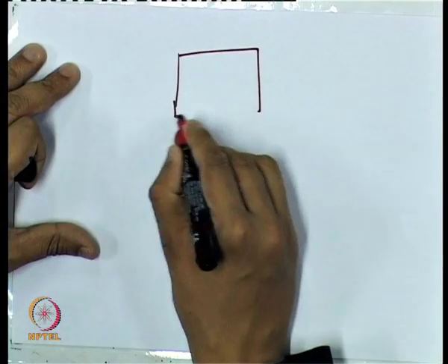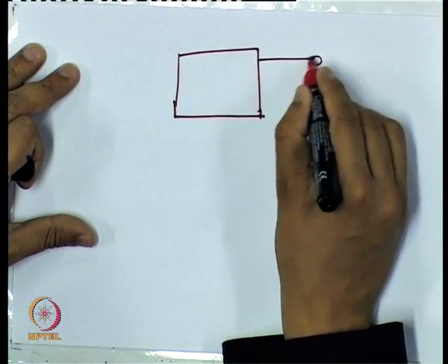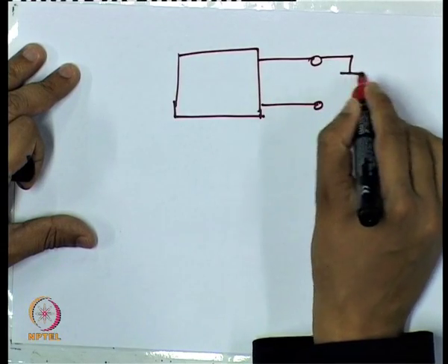Now, there are some other applications, since as I said, a two-port network is very extensively used. It is the most common form of microwave network. There are some unique properties or unique parameters associated with a two-port network that I would like to show you how to derive, and what is the necessity of that. So, one important parameter that is frequently associated with all two-port networks is what is known as the input reflection coefficient.